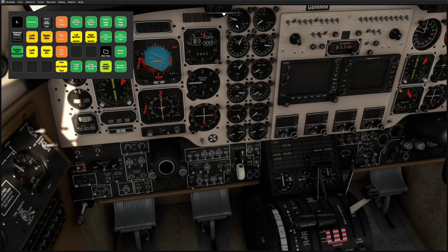We're checking that the ITT hasn't gone into anything too high. That's fine. It comes down now. Temperatures, pressures are okay. The ignition can go off now, and we should see the ignition happen. And we have.